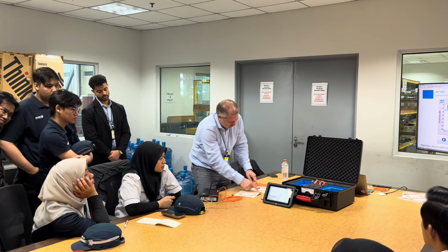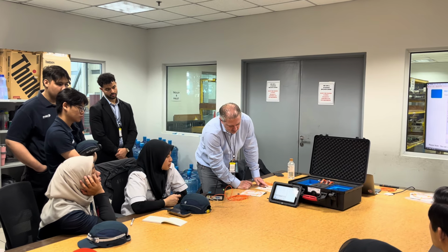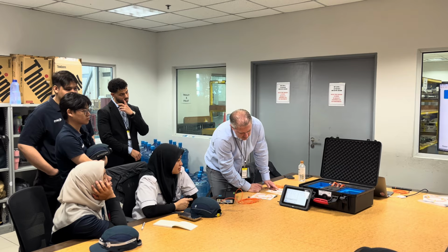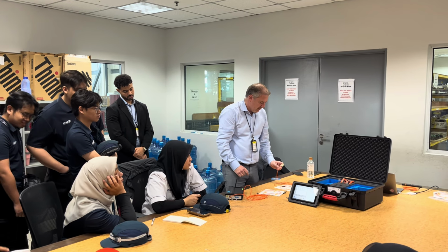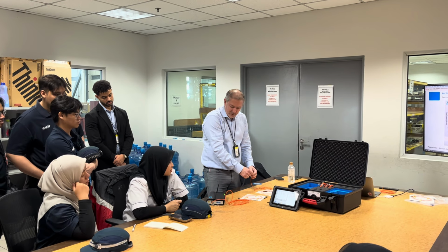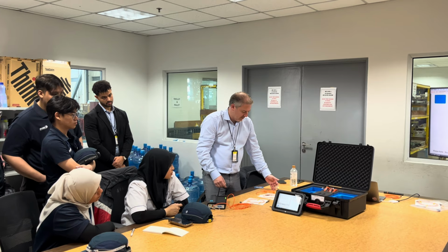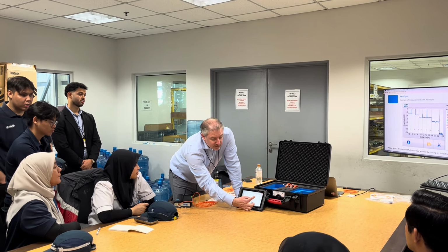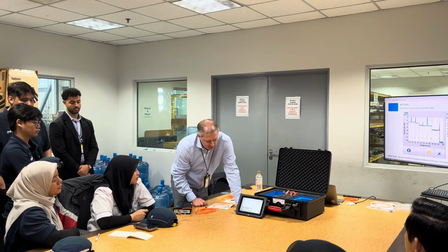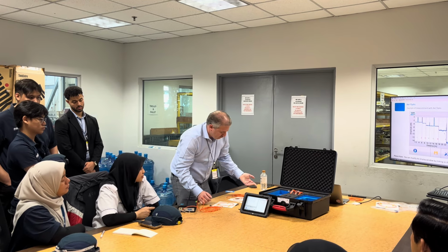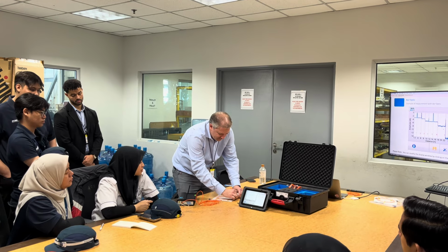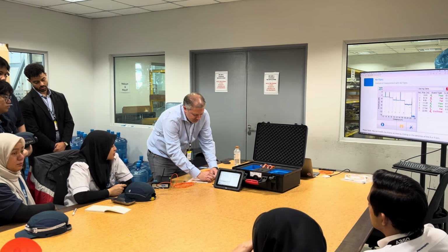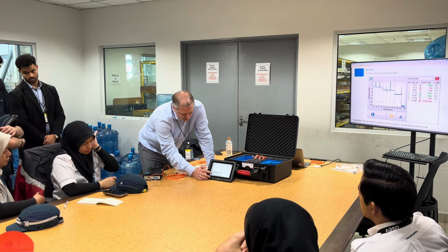Then I have 3 more meters, which is this fiber, and then this connector, which is good. This is very good, even 0. And then I have this broken fiber. So you see in this example, we put a piece of paper so we don't have infrared light going over there. So I have the broken fiber at 8 meters from this point. Okay. If we want to simulate a fault, for example, I can unscrew this a little bit, so I reduce the physical contact. I'll see what's gonna happen. So I can launch it again.